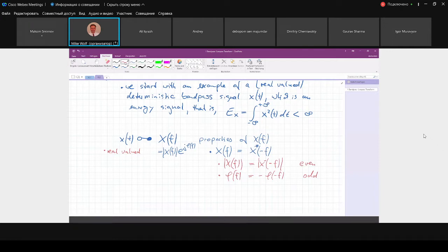And we can proceed even more. It just shows from a mathematical point of view that the left-hand side spectrum is redundant if we know the right-hand side spectrum and vice versa. So we can construct this if we know only one part. Now we use a certain notation, and this is really important that you understand it, otherwise you get stupid results. I denote the real part of this Fourier transform with a prime.